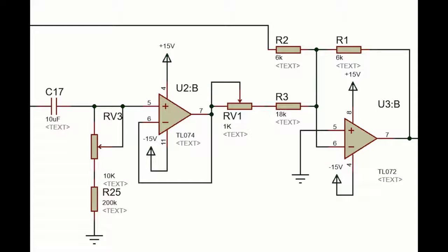I need to be able to automatically switch between using these signals depending on the situation. During a static or slow moving angle change, I need to use the inclinometer, hence the low pass filter.